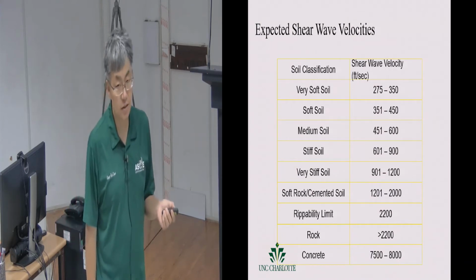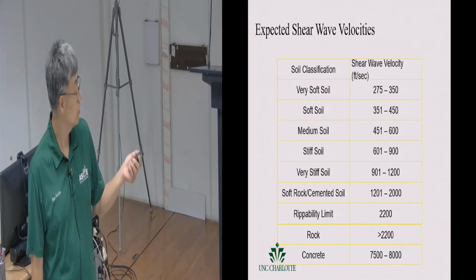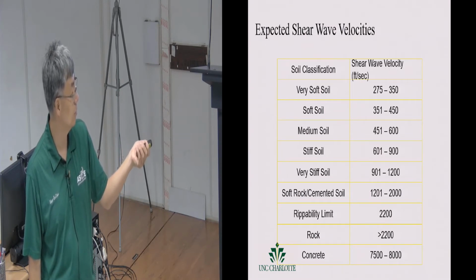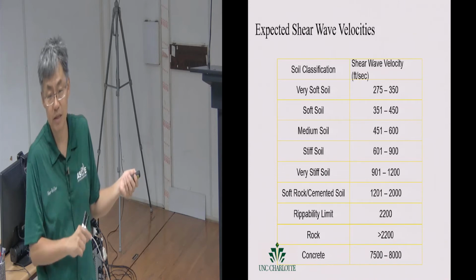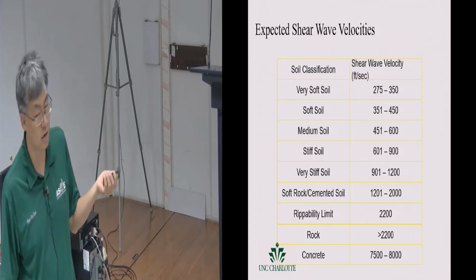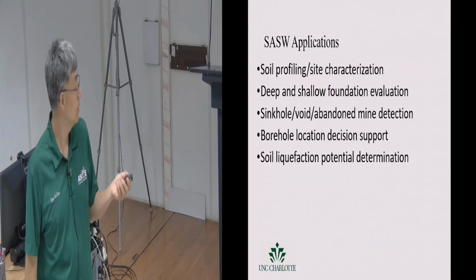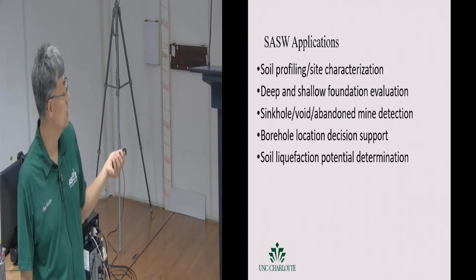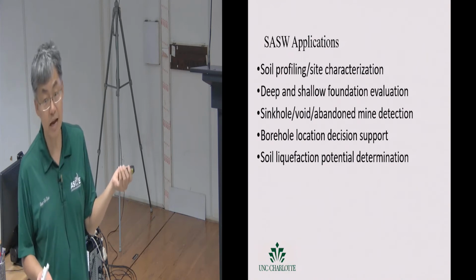And geophysics is much more rudimentary because soil is very complicated. Okay, so usually we base it on very simplistic guidelines like, you know, very soft soil. What does that even mean? Okay, but based on different wave speeds you can translate into the effects. Okay, and this is where this kind of technique is important, but the interpretation of the results heavily depends on your expertise. Okay, and so we have done this for many different applications, soil characterization to evaluate deep and shallow foundations, sinkholes, as I mentioned, which closely tie into abandoned mines.